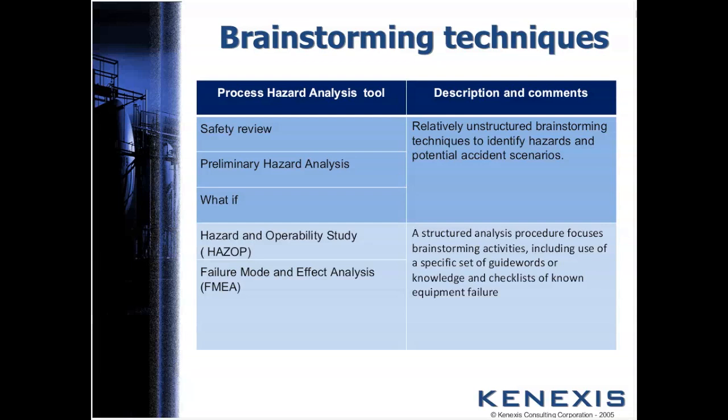conceptual basis. A what-if analysis is a brainstorming approach in which a group of experienced people familiar with the process ask each other questions and voice concerns about possible undesirable events that might occur in a process. Not very structured, but it is carried out in the industry at almost every stage of the life cycle of a plant. I'll talk about that a little bit more in a minute.